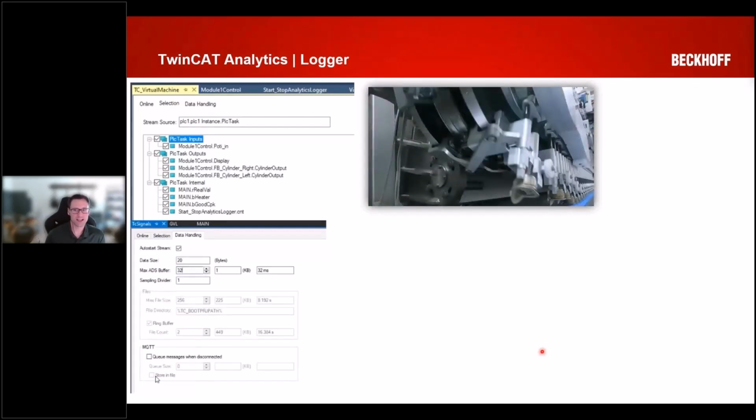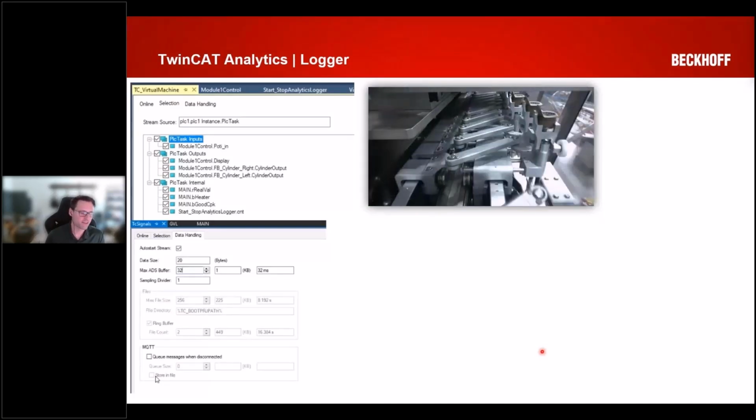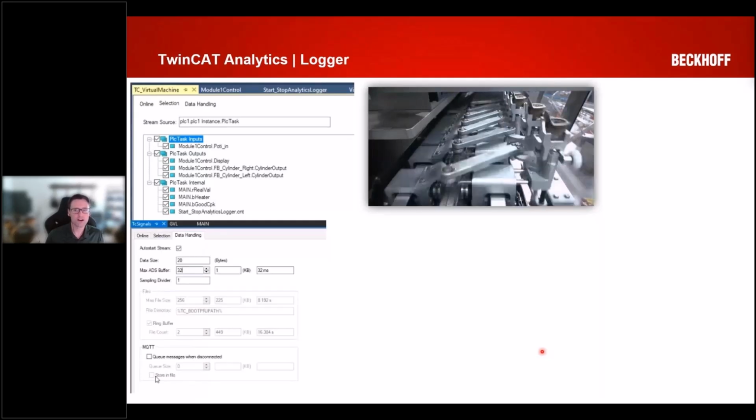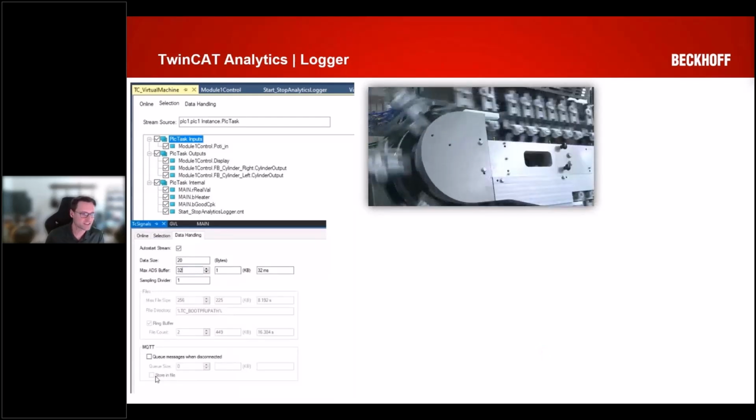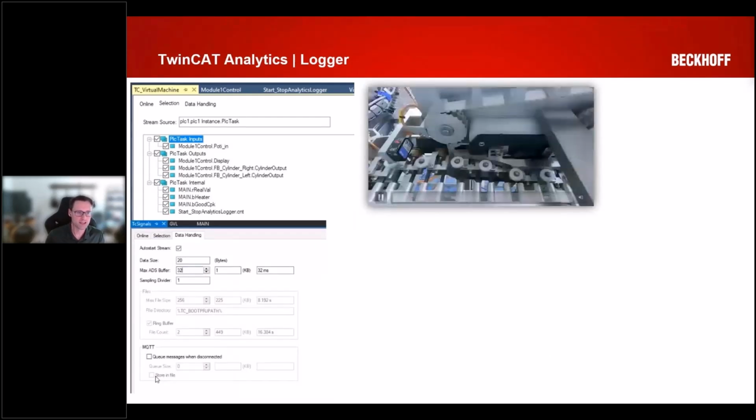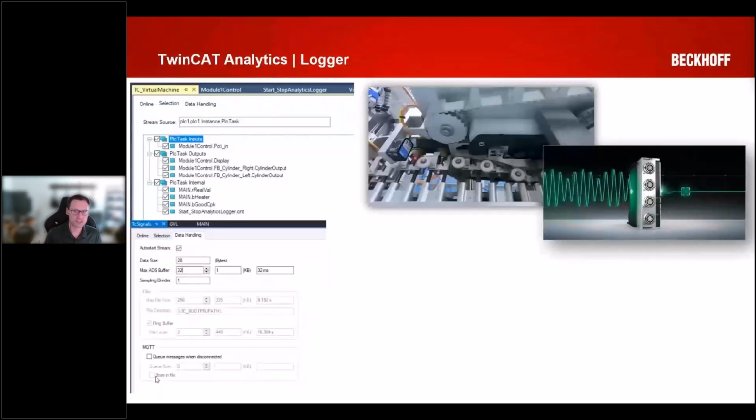Just to harp on the advantages of having that level of granularity, we already mentioned some, like program optimizations. If you have the exact state of your program for each PLC scan, you can easily track down race conditions. You can optimize motion profiles, things like that. You can combine this functionality with our measurement tools and oversampling terminals to realize high performance test and measurement applications.